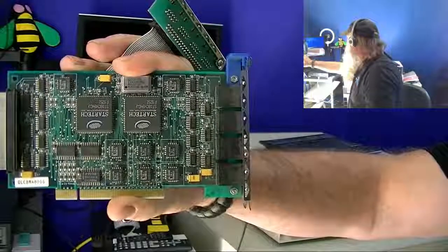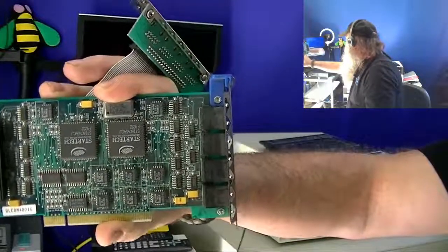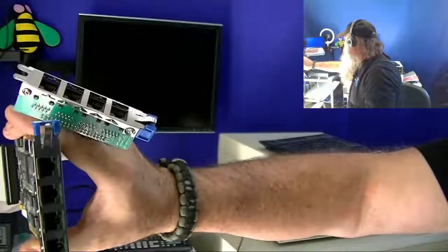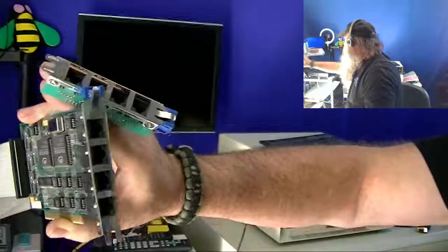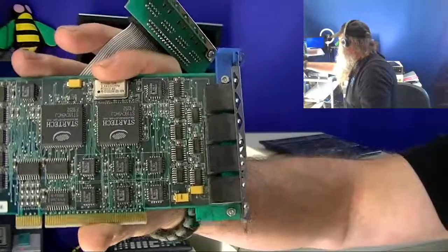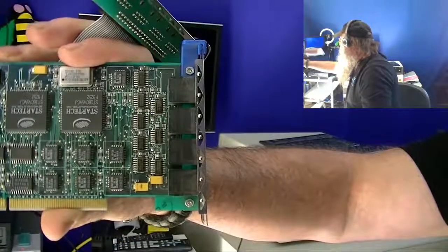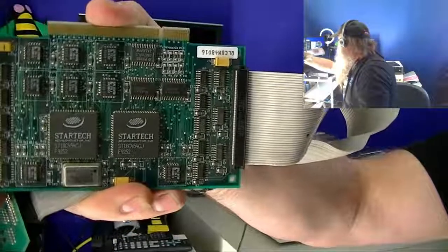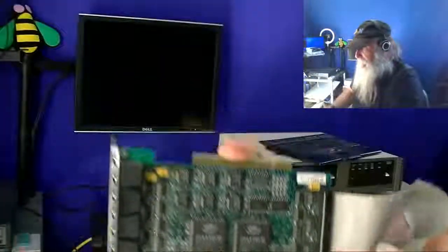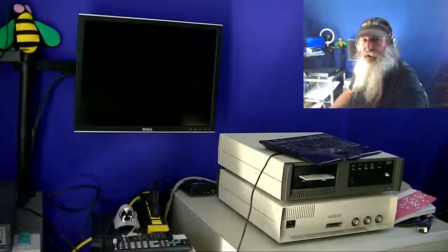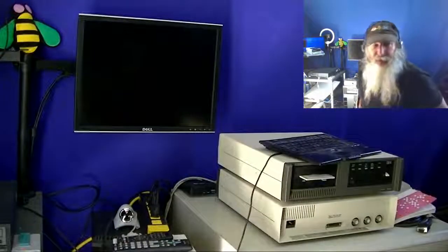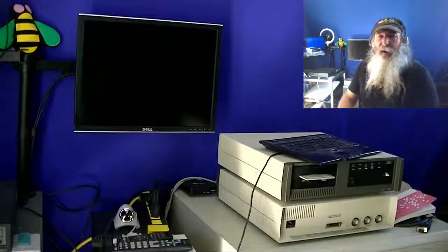I'll have to see what the challenge level of that will be, but this does not have an ADF out there that I've been able to find, and it's a fairly neat little adapter in that it's got those 8 serial ports, and it's relatively conventional in that it's got those 16C454 chips, to where those should appear as conventional serial ports, and microchannel having more ability for other I/O addresses of serial ports that should appear in the DOS low memory for the addressing and things like that.